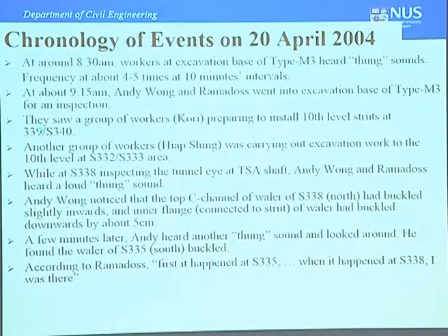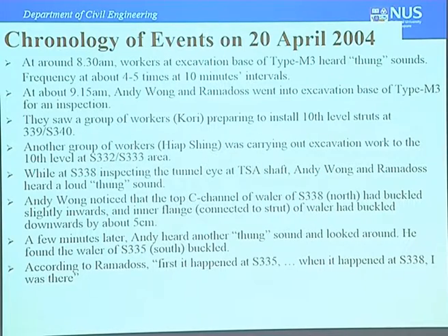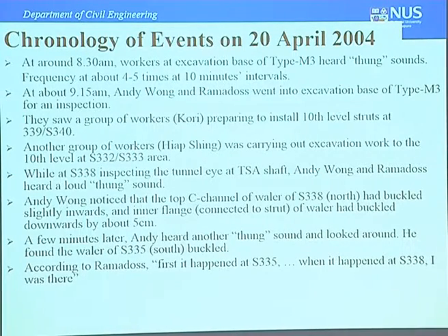Okay, anyway, you can see that there's a chronology of events. On the 20th of April 2004, around 8:30, they already noticed all kinds of sounds coming out. The joints were buckling, the strut whaler connections were all buckling. The struts were buckling, with a frequency of about 4 to 5 times in a 10 minute interval. Someone went into the excavation base for inspection. They saw a group of workers preparing to install a 10th level of strut. These are the strut sections. Another group of workers was carrying out excavation. They heard another sound. So a lot of this was going on already.